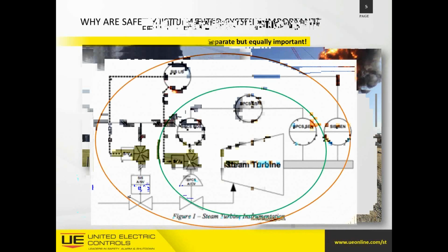The purpose of a safety system is to bring the process to a safe state. You may have heard this called in the past an ESD. We'll talk about that in a moment. Or permitting the process to continue in a safe manner when all specified conditions are satisfied. Some examples of that would be an emergency shutdown device, the ESD that I referred to just a minute ago. Safety interlocks, safety shutdown. Although many of us don't like to hear the word shutdown, sometimes it's imminent, and we'll talk about that. And then also starting permissives. Is the boiler good to start? Are our processes ready to go? Are doors closed and hatches closed when they need to be? These starting permissives are also very important.